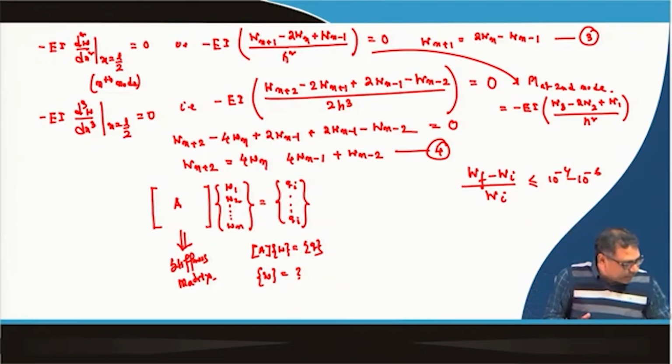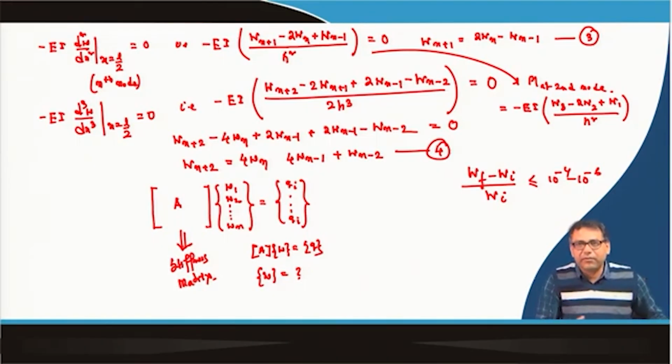This is the way you can solve the beam problem in the finite difference scheme, but this is for a beam with finite length. Similarly, you can use it for infinite length also by using the boundary conditions, because for infinite or semi-infinite length, your boundary conditions will change only, the equation will remain the same, because you need 4 boundary conditions.